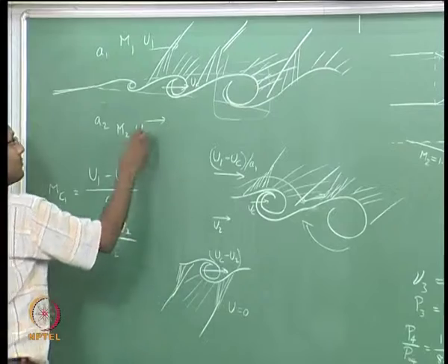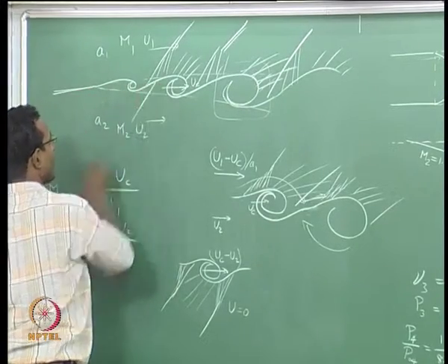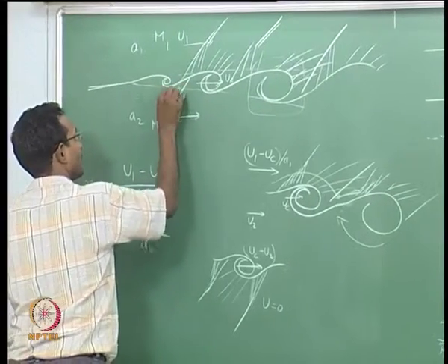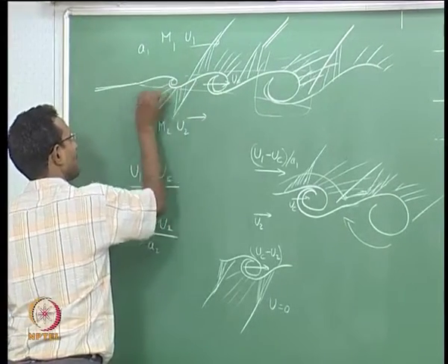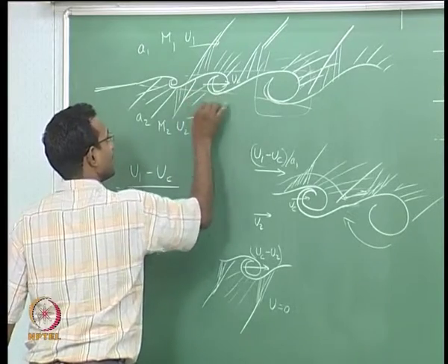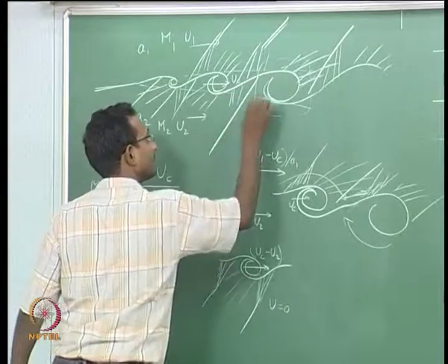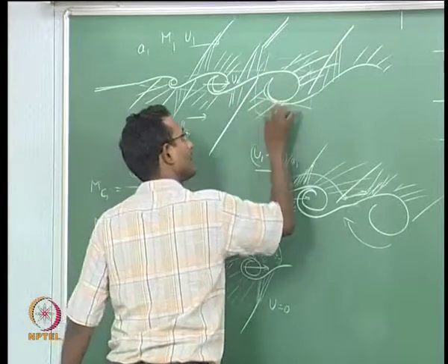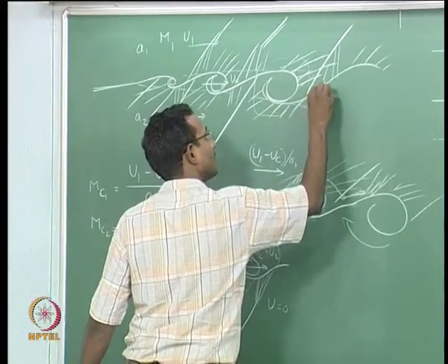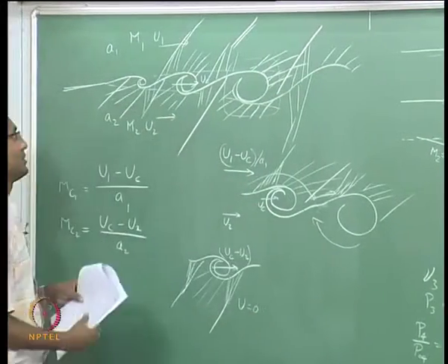On the bottom, this fluid is going faster than the outside, so there will be a shock, a set of compression waves, and then a whole bunch of expansion waves, and then another shock, and the structure repeats like this.